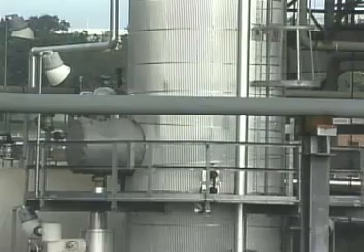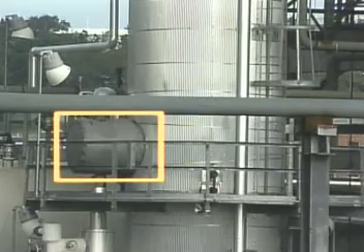Two major factors in achieving an energy balance are the rate at which the reboiler vaporizes liquid and the rate of vapor condensation in the condenser. If the system has a feed preheater, the heat that the preheater supplies must also be removed to achieve an energy balance. The energy flows are controlled by energy balance control loops.